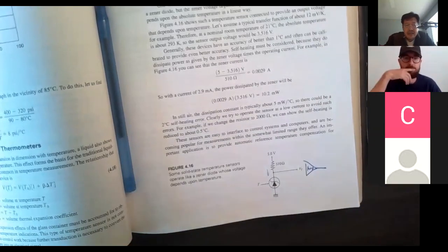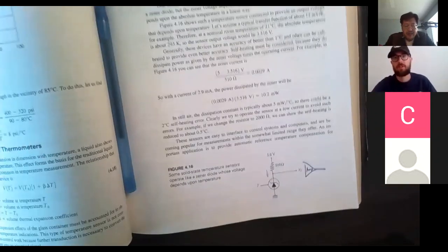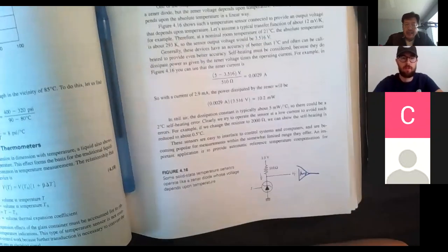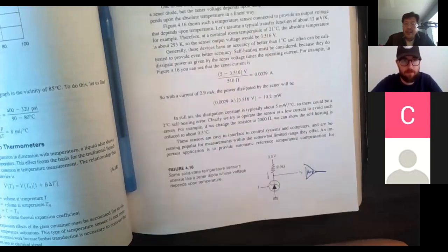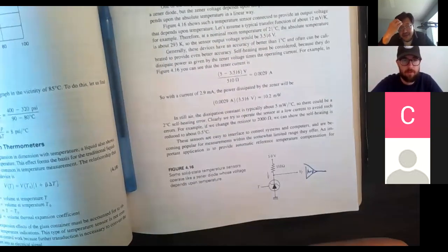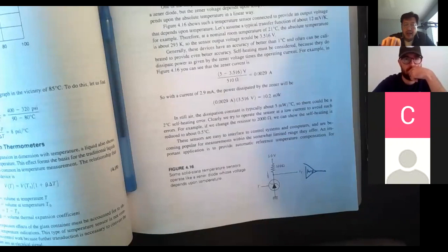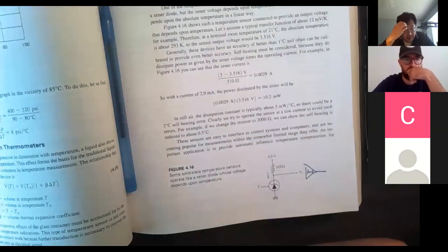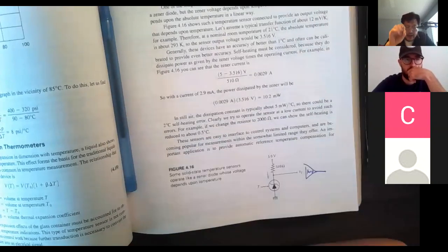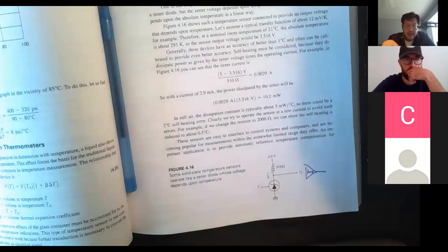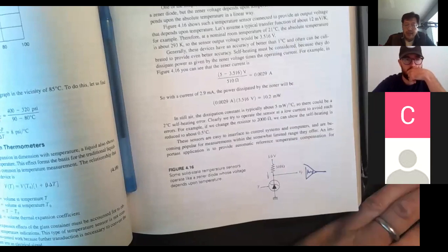And I met him later. He gave me the sensor. I asked, "Why does it cost $70?" So together we cut it open, and I'm amazed. Inside is the same sensor we use in our lab, plus a resistor. So inside is a resistor plus a sensor. It makes a 3-wire connection into a 2-wire one, so it's converted to a 2-wire sensor. I will show how to make that conversion Wednesday. Once we cut it open, we knew we don't have to spend $70 anymore.